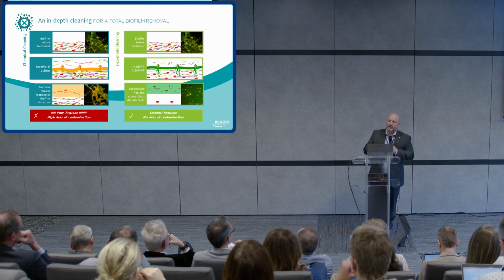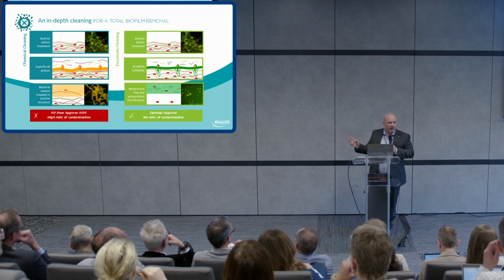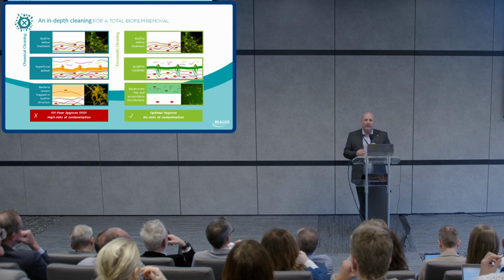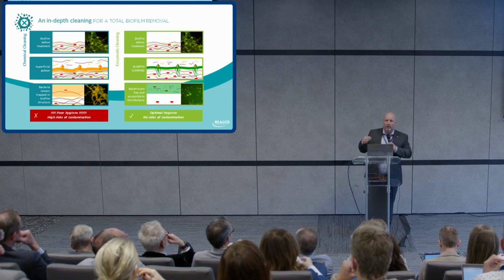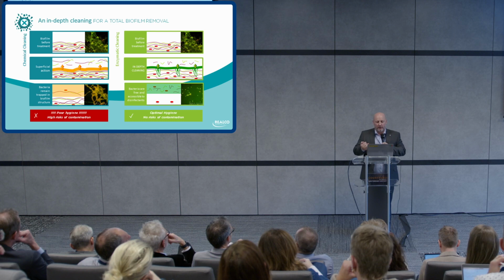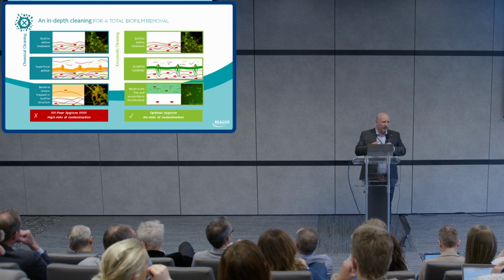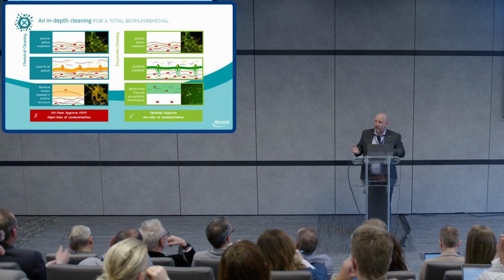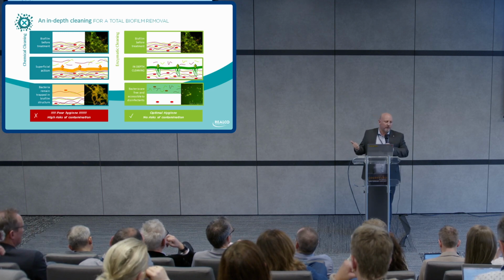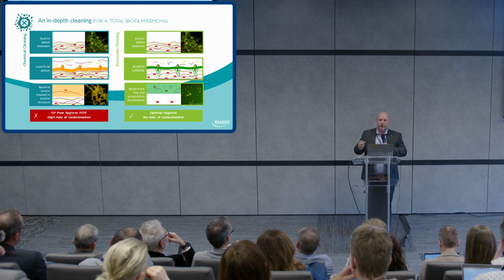I'm not saying that you all have resistant biofilm in your facility. Some biofilms are easy to deal with using water or alkaline-based products, but we act on those that are resistant to standard solutions. So if you are not capable of getting rid of biofilm via standard solutions, okay, it's maybe because it's a biofilm that resists those CIP and SIP.